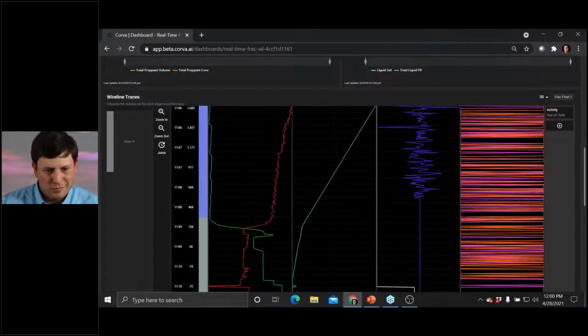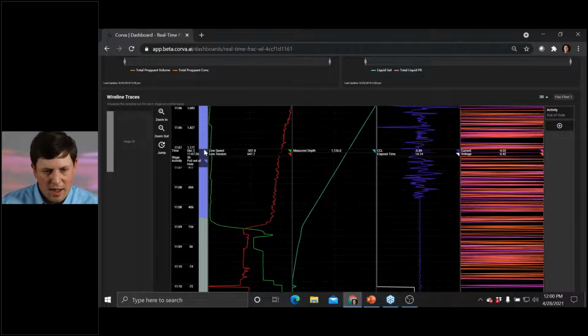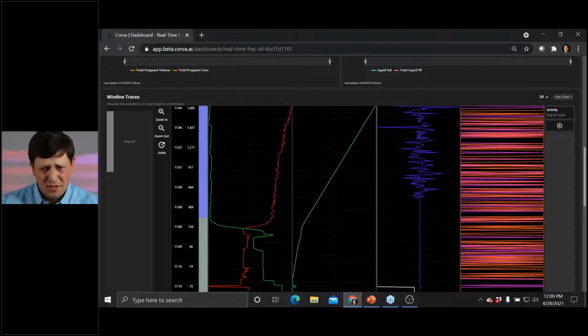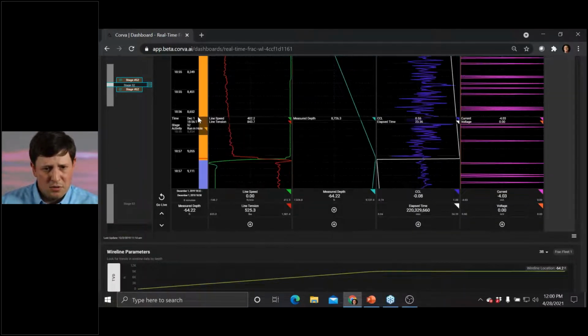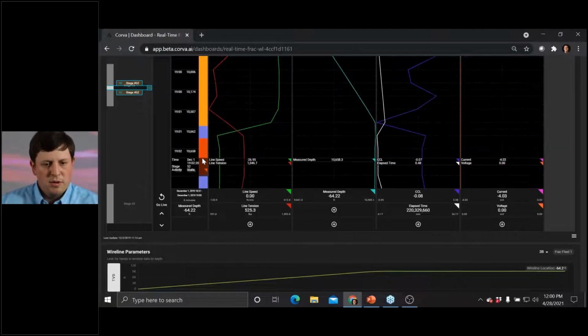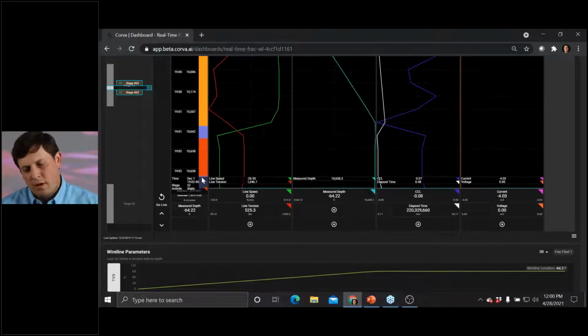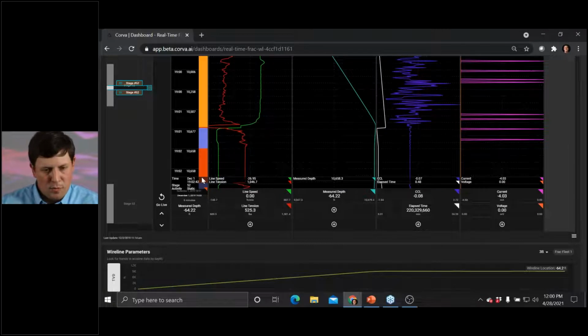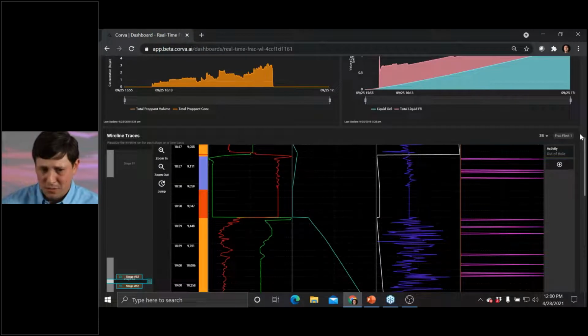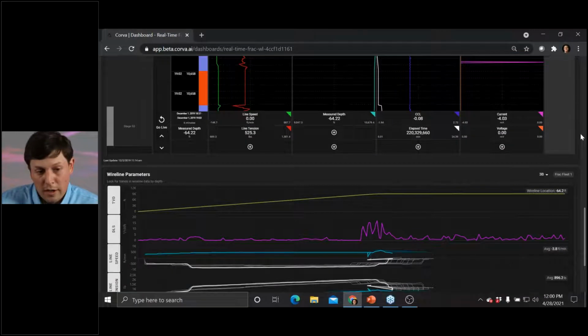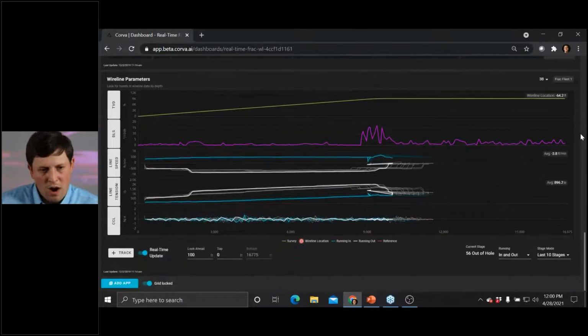Another thing I wanted to correlate, just like before, is that we have an activity detection piece for this side. So if I move this up just a hair, you could actually see when you're running in hole, when you're static, when we're pulling out of hole. Our activity detection, based on the real-time streams of information and those thresholds, can actually tell when you're in and out of the hole. So again, it automates that entire process, feeds into the analytics, but also serves remote monitoring purposes, which are currently used by customers.